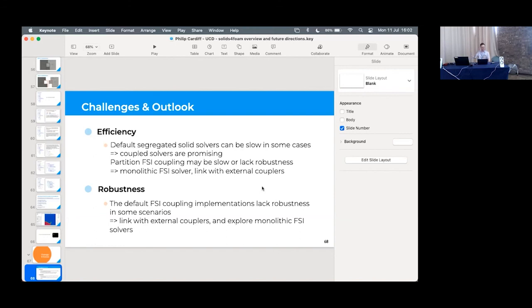Yeah, so in solid models and Solids4Foam, some of them have a prefix name that starts with uns. It's a different discretization of the gradient at the face. So this comes from Jasak Jukovic. He came up with some methods where if you want to calculate the gradient at the face, there's a couple of ways to do that.